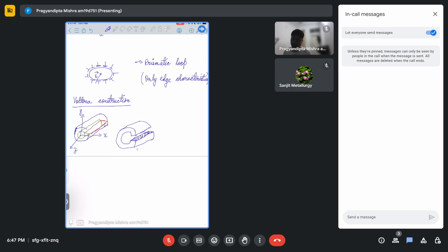Okay. So I've cut and I've moved them apart. I moved them in, translated them along the y direction. I've moved them apart, right? So this leads to the Burgers vector being perpendicular to the dislocation line, right?